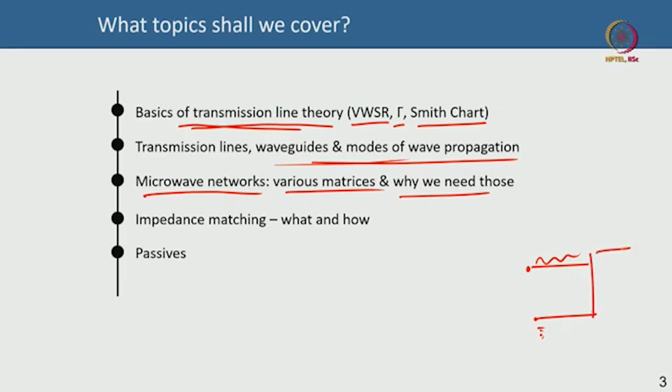So, for instance this is your gate and this is your source. A signal is coming in here. So, this is your input port. It is not like the signal is only coming here and this is grounded, it will come and it will go back. Both of them reinforce each other, but phenomenologically you can say one of them is source, grounded, and one of them is bringing the signal. So, this is a port. Similarly, on the output side there is drain and then there is source. So, the output is with respect to the source, between drain and the source. So, it is a 2-port network. So, transistor, a 3-terminal device, is a 2-port network.